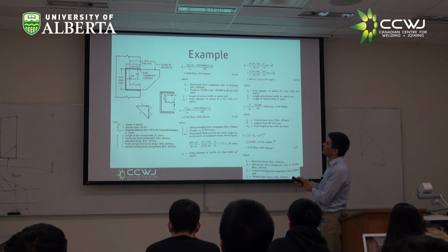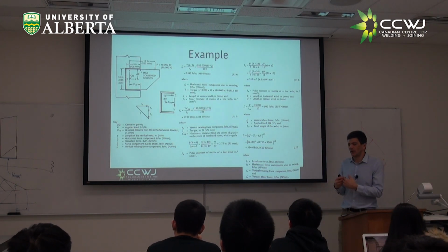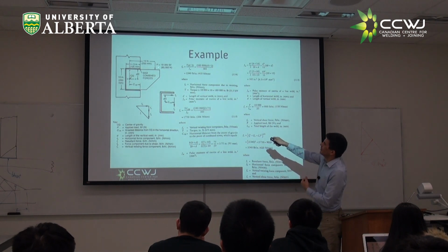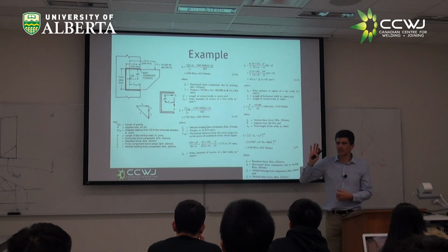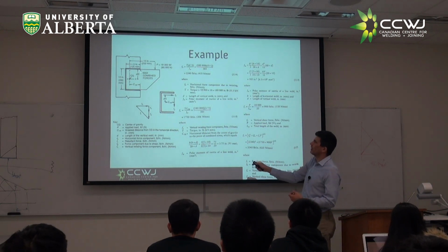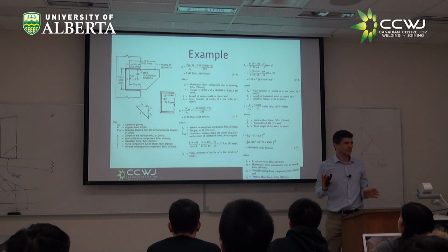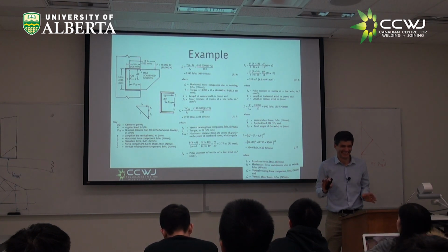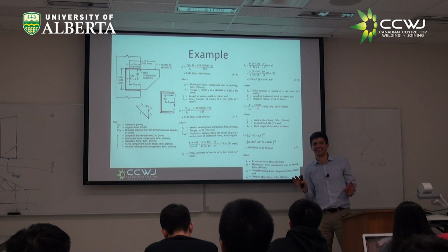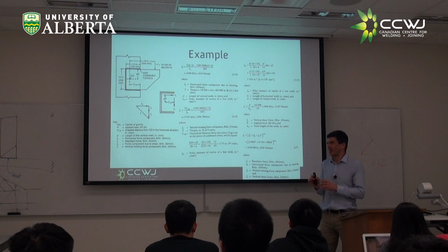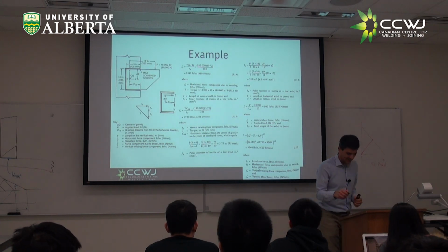So this is the way you go. You calculate the force that the weld needs per unit length for each of the stresses it has. For example, if I put this force here, this is going to generate some twisting, right? And if it generates some twisting, there is going to be some horizontal force in here. Are you all with me on that? Or not? Oh, the crickets are deafening. Okay, let's do it. I care that you get it.